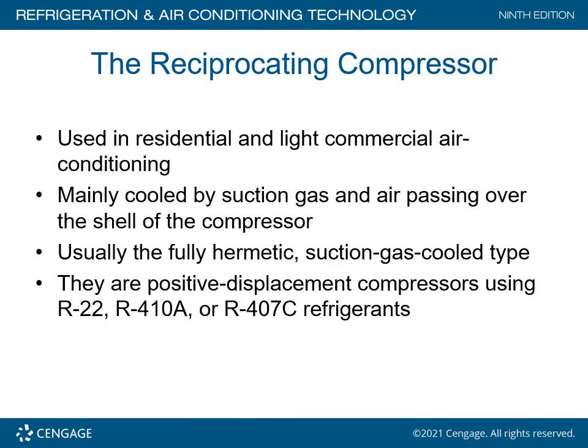Reciprocating compressors are utilized in residential and light commercial air conditioning, mainly cooled by suction gas and air passing over the shell of the compressor. Usually they are the fully hermetic, suction gas cooled type. These are positive displacement compressors utilizing R22, R410A, or R407C refrigerants.